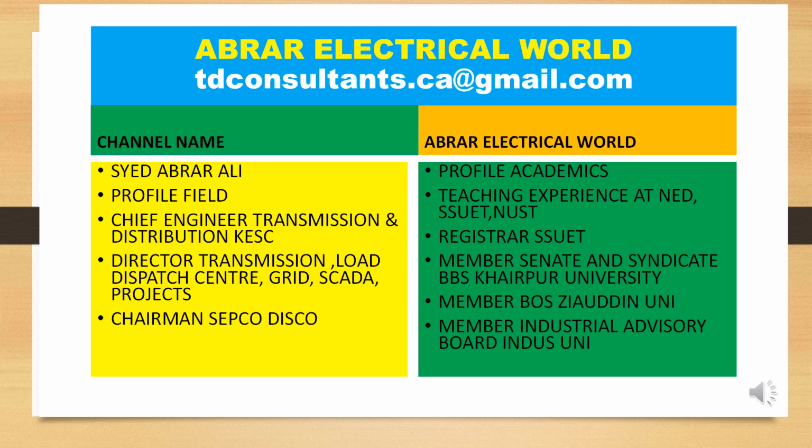And one thing most important: distance protection is a non-unit protection. It is not a unit protection. Remember, differential protection is unit protection, and this is non-unit protection. This is a very confusing question because the engineer and the student think that it looks into the line in one direction and takes care of the faults on the line, therefore it should be a unit protection. No, it is not. It is non-unit protection. It does not have a specific line of its own for protection, like a transformer has for differential protection, which is a unit protection.